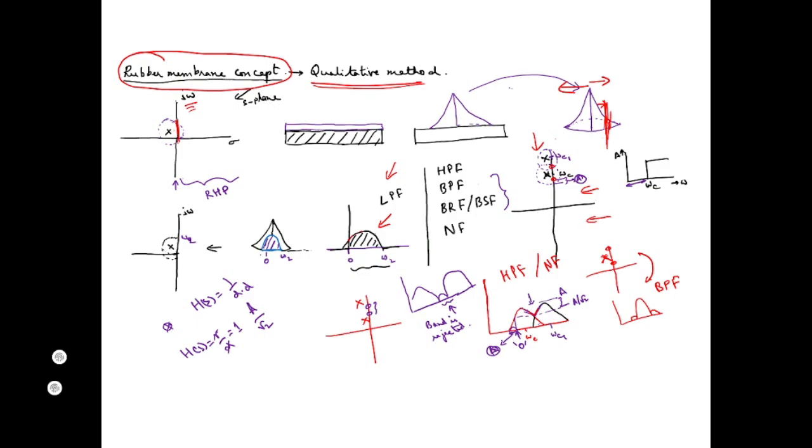If you take that same pole, you are just changing the alpha value, and alpha value means the real value, without changing the j omega value. You are moving the pole away from the frequency axis, and the frequency response will come down at the j omega axis. Okay. So also in the other points, but the main effect will be on the j omega axis. Okay.